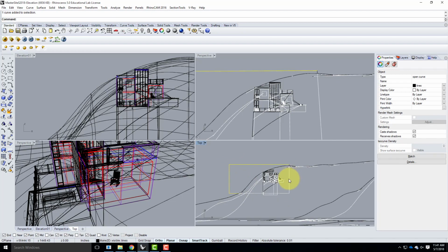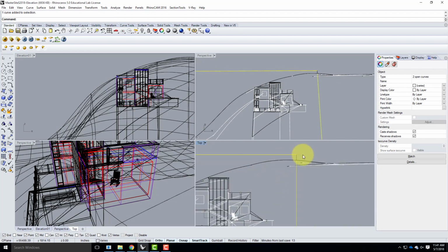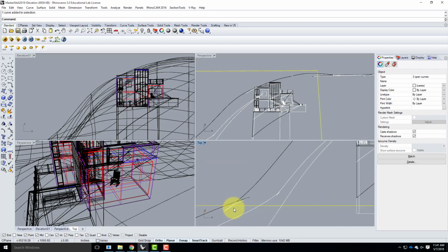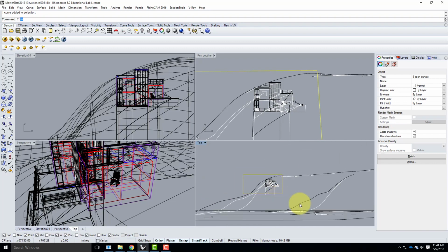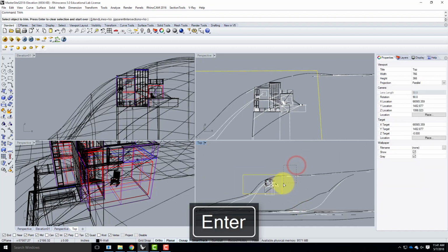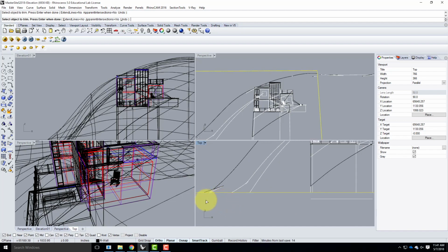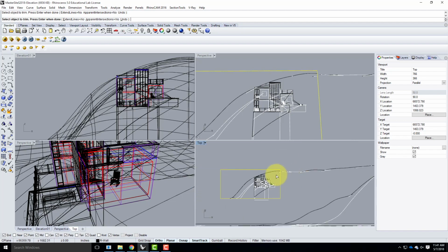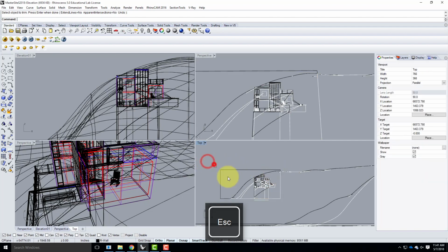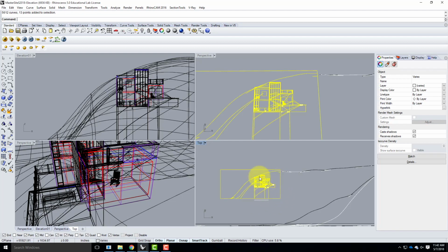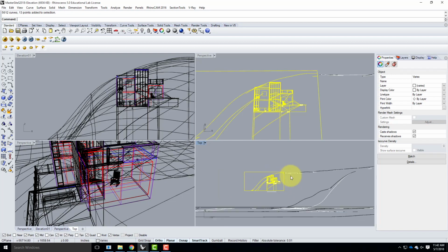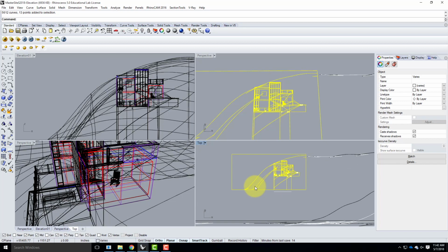I don't need that rectangle. So I'll go ahead and select the rectangle itself. There it is. I'll type trim, and we can get rid of the stuff outside of the rectangle. Perfect. So I got rid of everything outside of the rectangle. I'm going to take that rectangle, which again is my view, and I'm going to move that rectangle to 0,0,0.